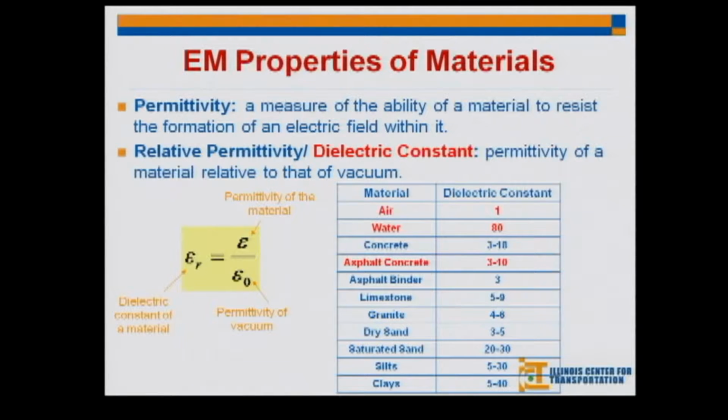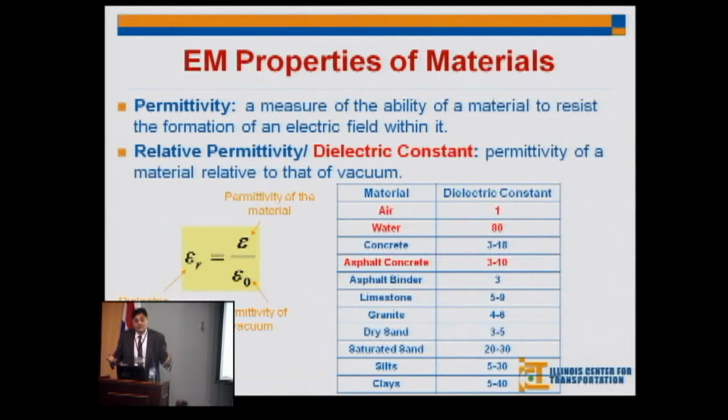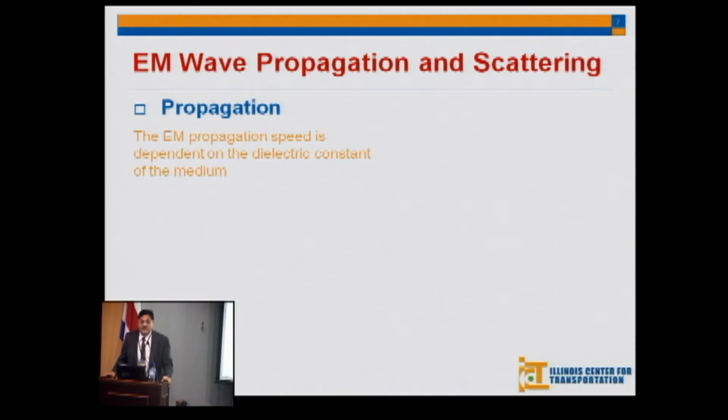Then you get into materials like the silt and clay, and the clay is actually the toughest, because sometimes the clay has water that is completely adsorbed, not absorbed, adsorbed, which means that it's chemically attached to it, and that doesn't allow it to move that much. So the dielectric constant will be low. But if there is free water in the clay, then the dielectric constant will be high.